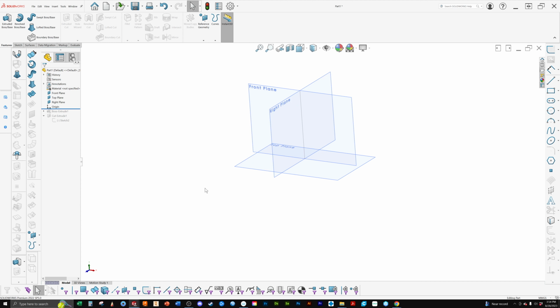And one of the things that I'll try to drive into you guys is how important it is to be detail oriented. You can get away with some sloppy 2D sketches in solid modeling, but as we progress and you get into doing lofts and 3D surfaces, the sketches are so important because without a good clean sketch, the commands will fail.